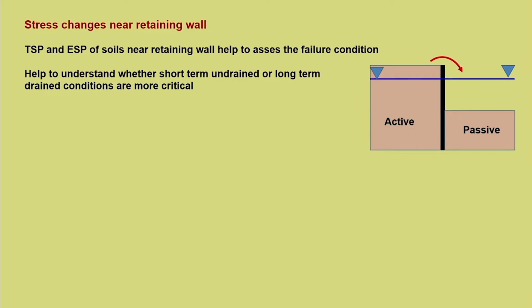So, whether it is moving towards or away determines whether the given structure will be safe in the short term or in the long term. What determines this? Essentially, during the undrained condition, the kind of pore water pressure that gets generated, positive or negative, determines in what direction the effective stress path would move further.